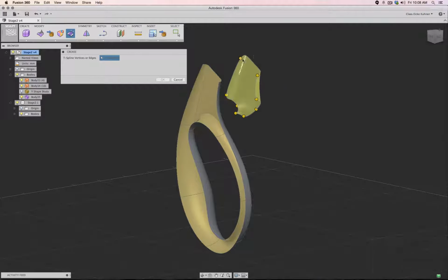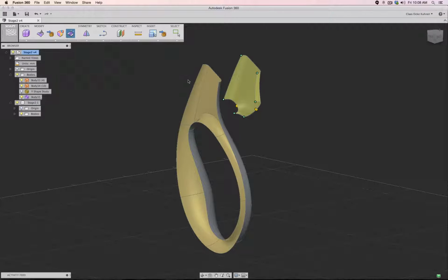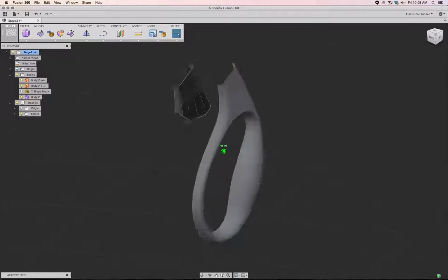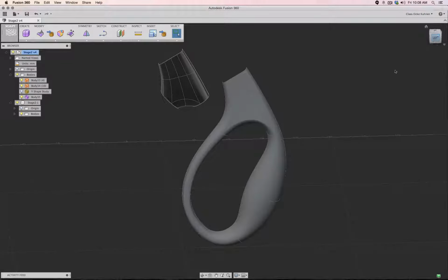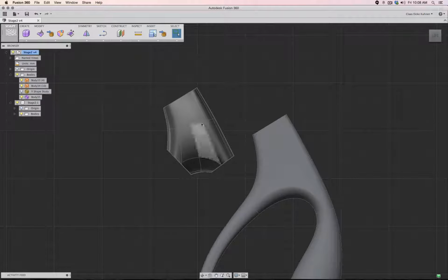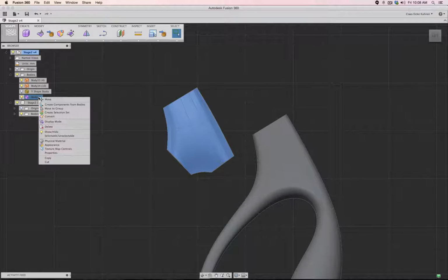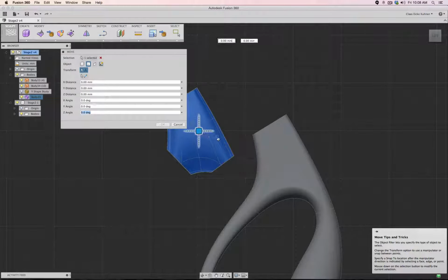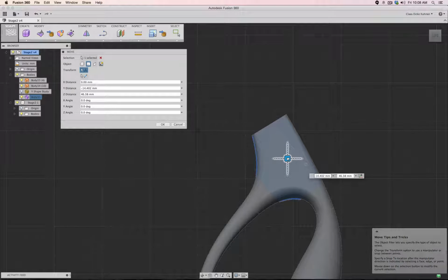And in T-spline to crease, I can click on edges or I can click on corner points. It's pretty much the same what I did in Blender. In T-spline you only can crease or uncrease. In Blender you can have a weight at the moment. And now I would like to position this one, of course, so I can click this object, right click, move, and for example move it to somewhere there.